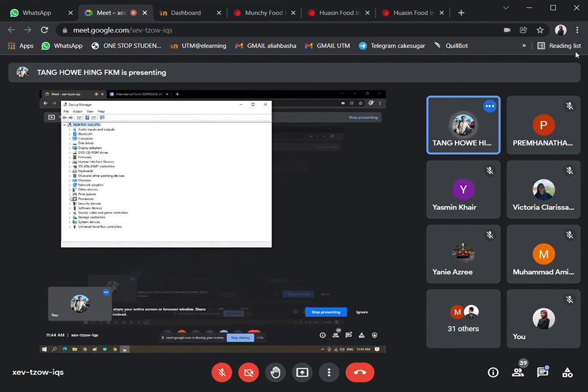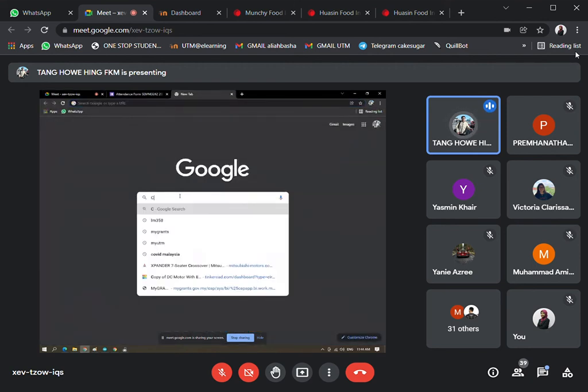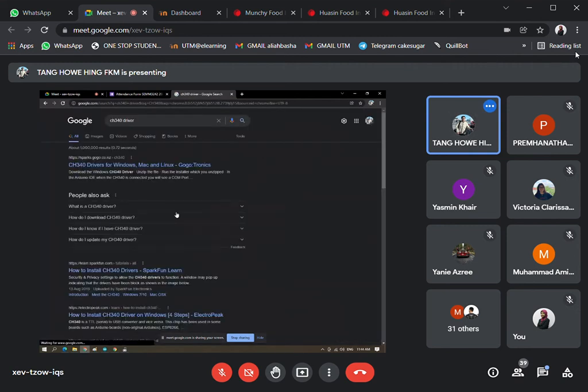You can see this USB serial port, there are some issues over here. Because I'm using the Uno board by Cytron, supposedly it shouldn't be using the CH340. But never mind, I think I'll just install the CH340 driver.